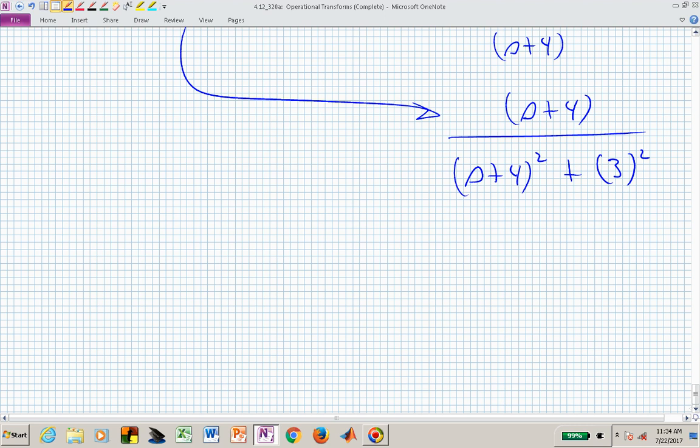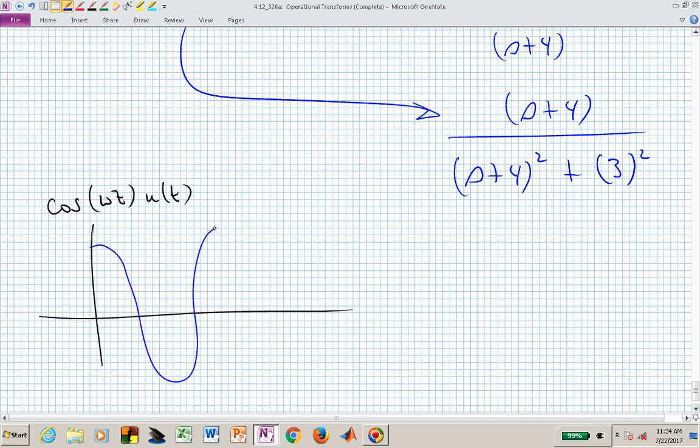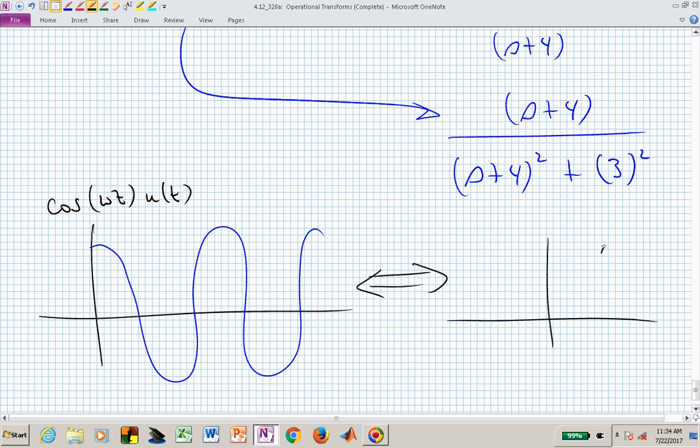And you can think about what we have in terms of, if we looked at the standard waveform, which is cosine omega t u of t, assume that that's a constant omega, then that produces in the frequency domain a pole zero pattern. There's no exponential damping, so that now we have a zero at the origin, and we have poles at j omega and minus j omega.